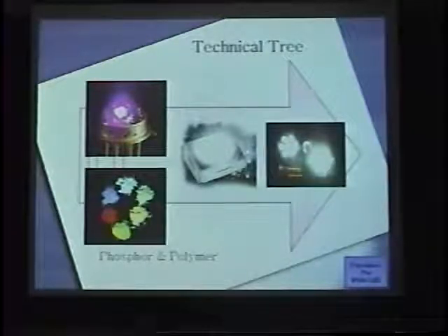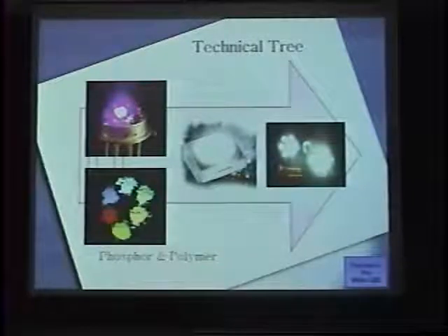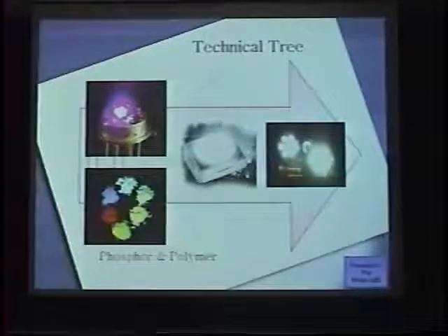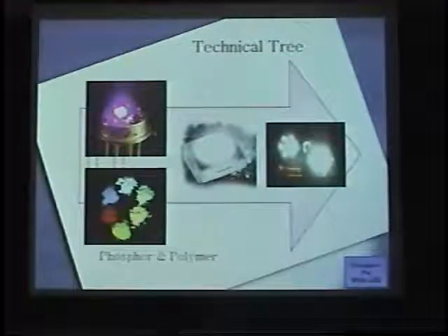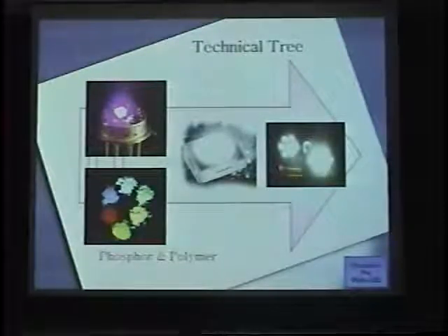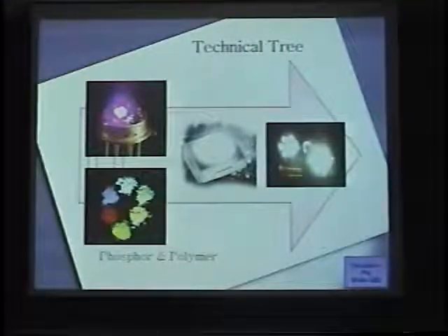Phosphor materials. Also, we need a polymer encapsulant. In this case, the refractive index is very important. The gallium nitride refractive index is 2.0 something. So in order to take the photons out of the gallium nitride, the refractive index has to be similar to that of gallium nitride. So we need to increase the refractive index of this encapsulant. What about the big issues with these phosphor materials?